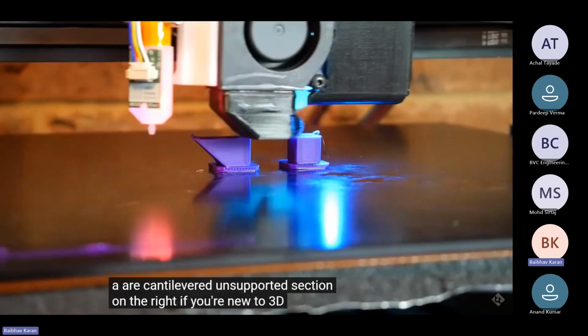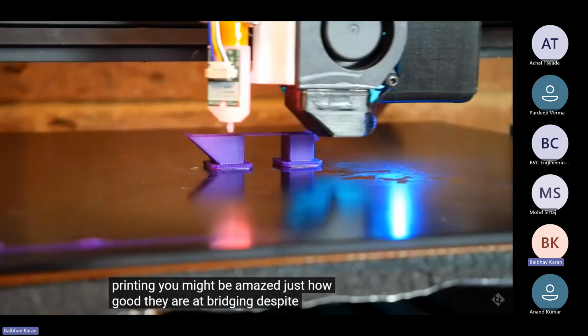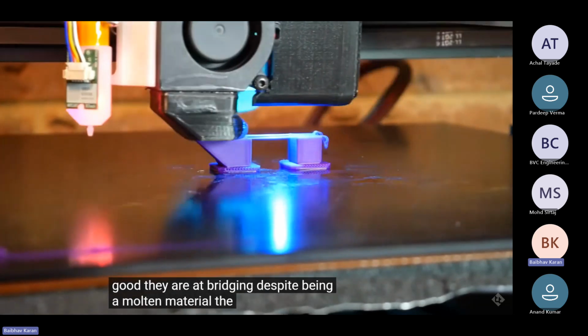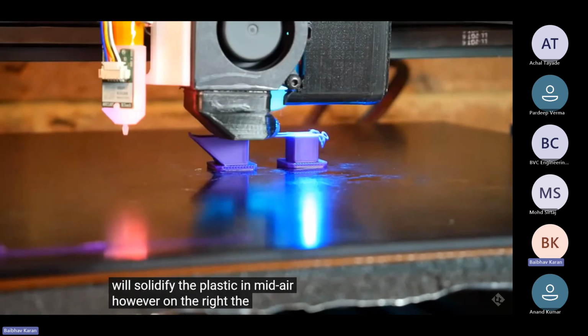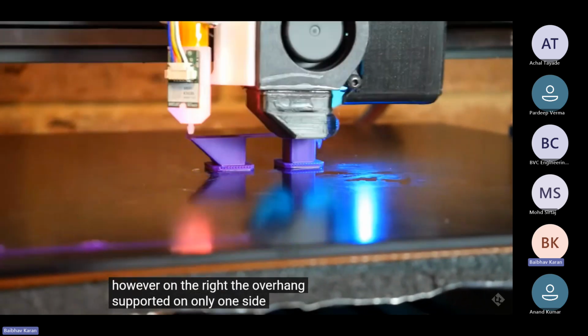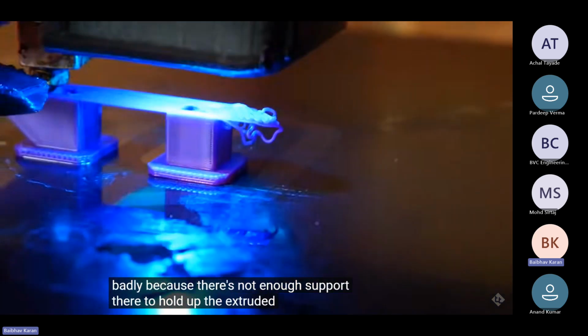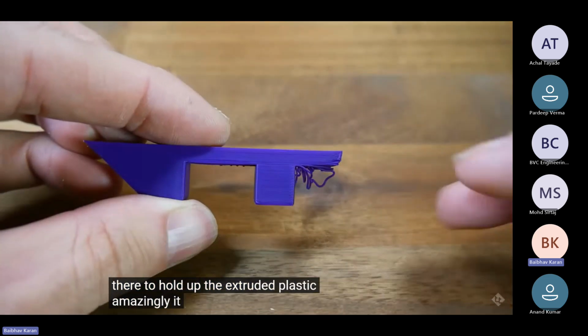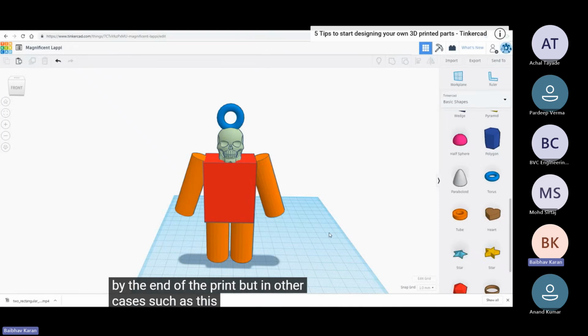If you're new to 3D printing, you might be amazed just how good they are at bridging. Despite being a molten material, the part cooling fan will solidify the plastic in mid-air. However, on the right, the overhang supported on only one side is drooping badly, because there's not enough support there to hold up the extruded plastic. Amazingly, it does recover quite well by the end of the print, but in other cases, such as this key ring, we won't be so fortunate.